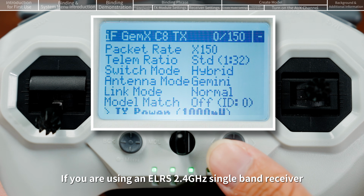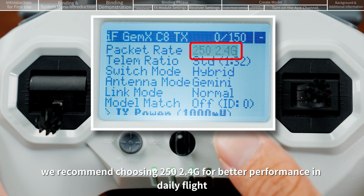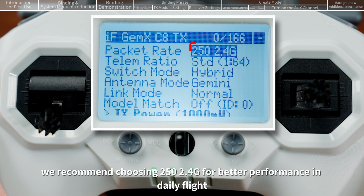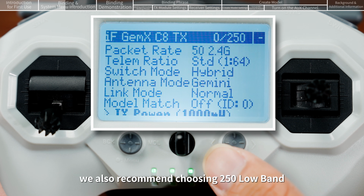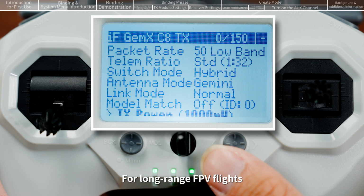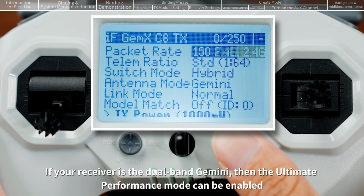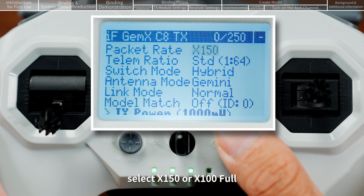If you are using an ELRS 2.4 GHz single-band receiver, we recommend choosing 250 2.4G for better performance in daily flight. If you are using a 900 MHz single-band receiver, we also recommend choosing 250 low-band. For long-range FPV flights, select downward to the 50 low-band mode. If your receiver is the dual-band Gemini, then the ultimate performance mode can be enabled. Select X150 or X100 full.